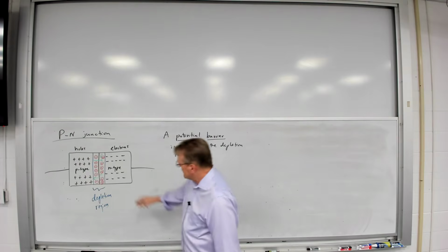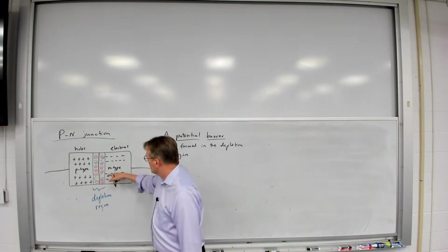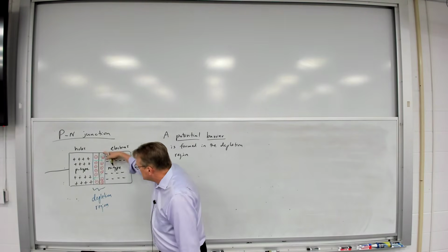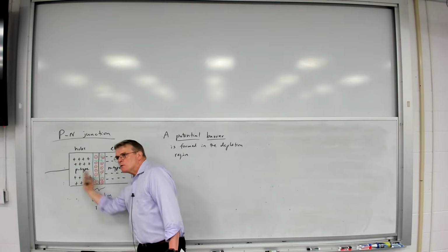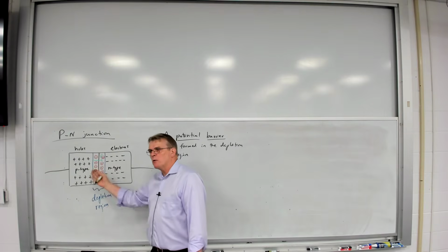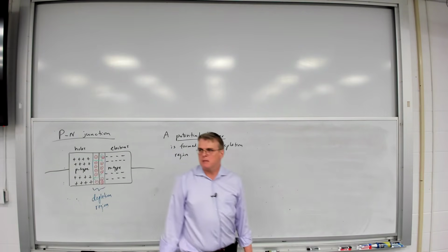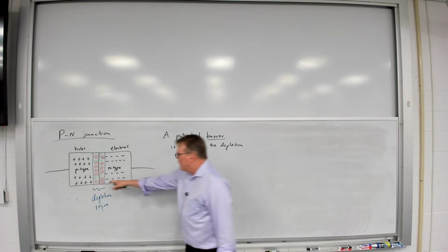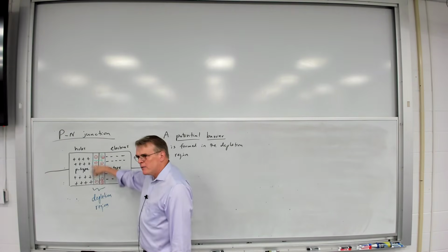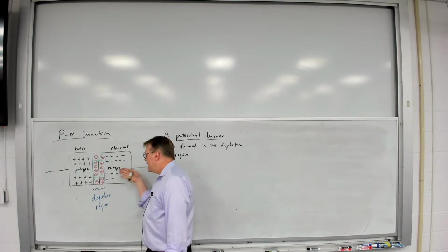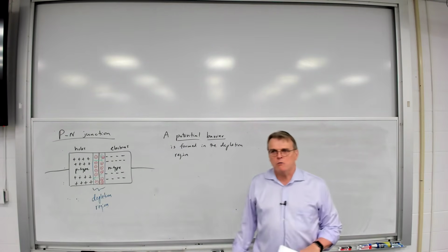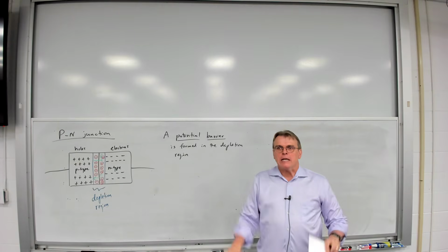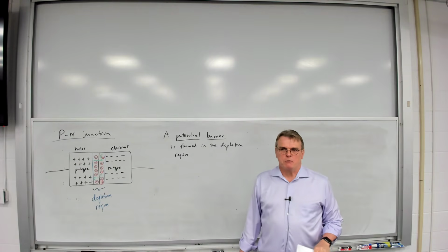And what happens is this. As this potential barrier forms, you start to accumulate positive charge on this side. The positive charge starts repelling the holes away, any additional holes that try to come across. It pushes them away because of that positive charge. The negative charge starts to accumulate on this side. It starts to repel any more free electrons. So as that potential barrier is formed, it halts any additional diffusion, any further diffusion.